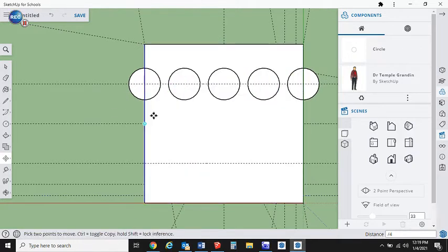So there's a few ways we could do. We could select all of these and copy them down, or we can just repeat the process, which seems to me to be the easiest way to do that. Oh, I spoke too soon. Selected my edge of the line instead of the center of the circle. There we go. Remember, if you make a mistake, Control Z or Alt Backspace are the shortcuts to undo.